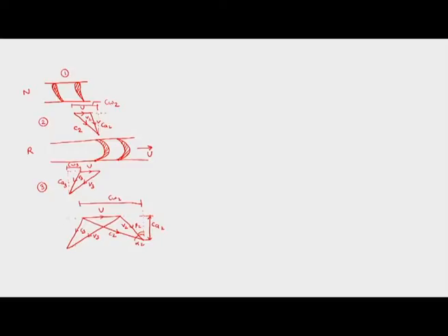As a virtue of this, we should have the height of the triangle be the same at the inlet and at the outlet, since we expect the flow to be going in the same axial direction with the same velocity. So this is V3 and this is C3.